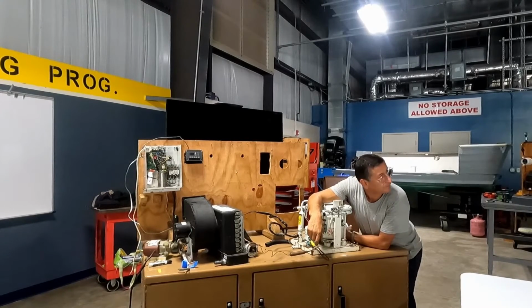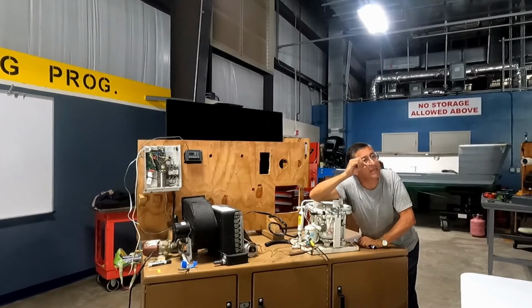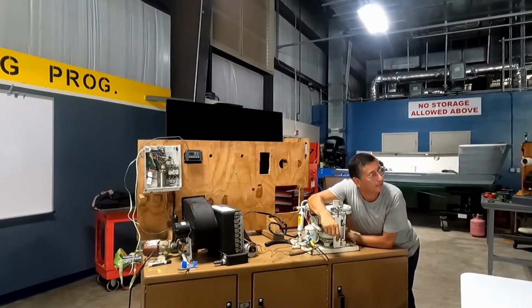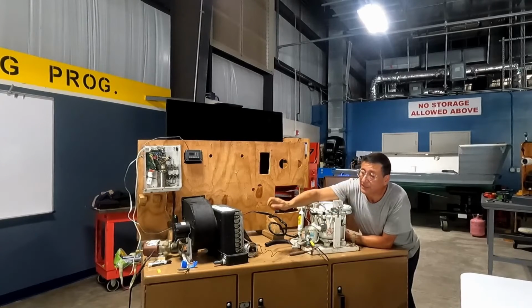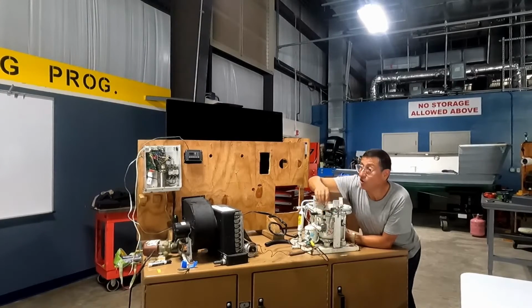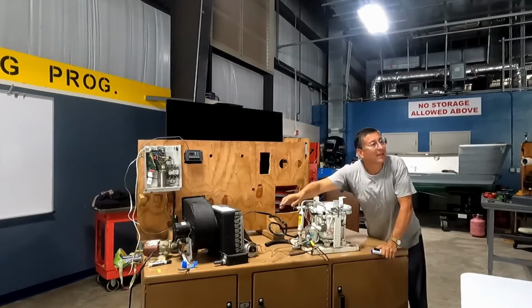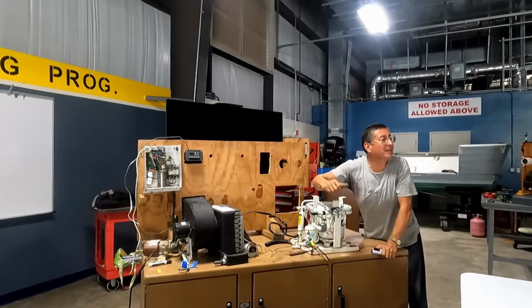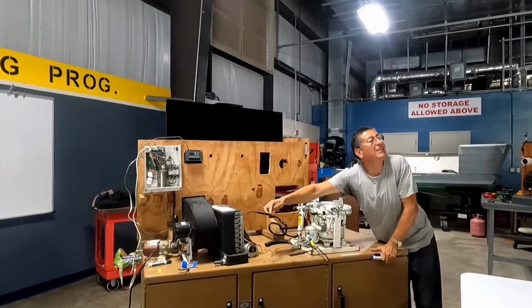Are the lines a specific length to make sure that it's... Yeah, the length and the diameter are specific. It's calculated according to the capacity of the evaporator and the capacity of the compressor. Pay attention, my friends. At the bottom of the evaporator, the refrigerant enters and starts to evaporate. The warm air, because I have the ambient air of this room, helps in that process to evaporate the refrigerant. When the refrigerant goes out here, it's completely evaporated.